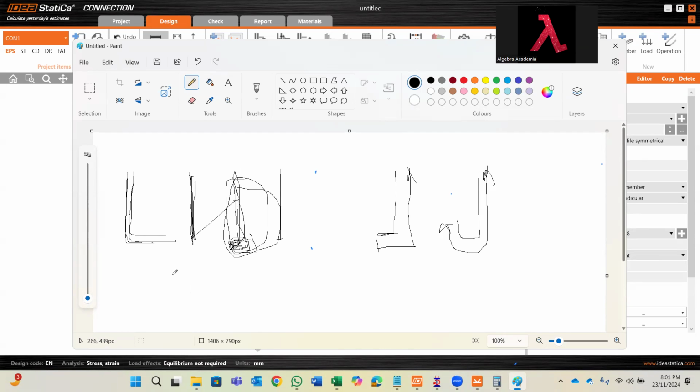When I have a beam here, I will take the top bar here and here, right? The development length from here to here, this is the development length, but people are misunderstanding the concept. You're 100% right, this is the development length, but the code gives two different kinds of equation. When you go for a hook, you need to use a different equation to calculate the development length.